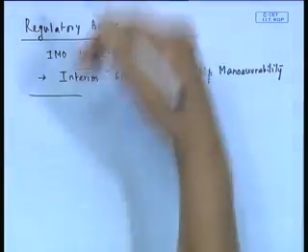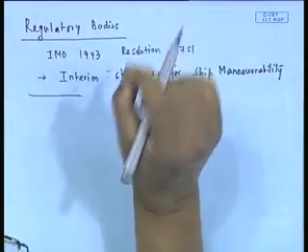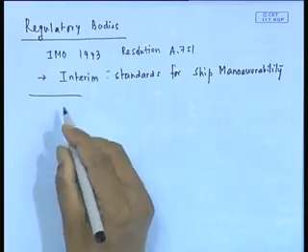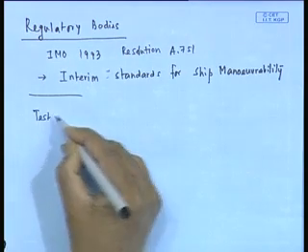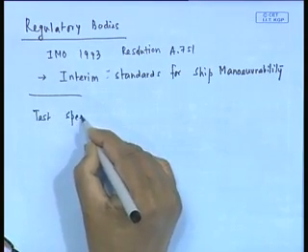So there are some rules given. It applies essentially to the zigzag maneuver and turning maneuver and also the stopping trial, but I will not tell that. In other words, basically you have to make sure that your ship is within those limits. Why am I saying this? Because you will find that the limit in zigzag especially is not that you have a very highly maneuverable ship. Basically there are limits on both sides. So here some of this is like this. The test speeds, the important one only I am writing.